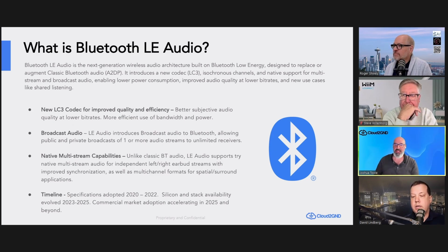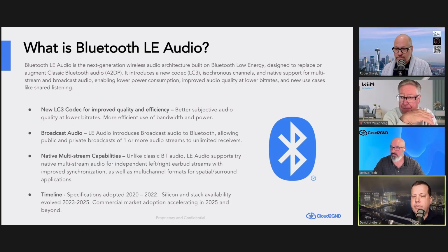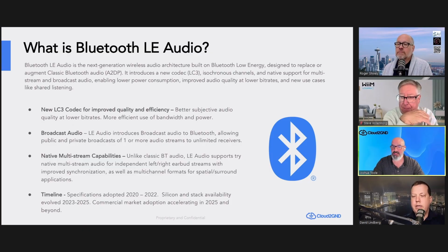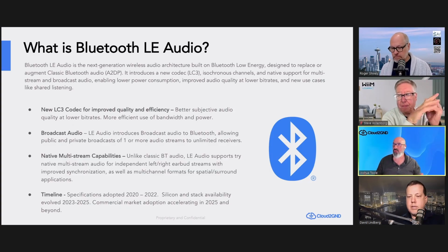So you had Bluetooth LE, which was originally driven for sensors, fitness devices, low power devices, like the initial market. Nordic stuff, all that? Correct. Nordic is one of our partners, and they produce exclusively LE based chips, so they don't support what's called dual mode. Basically, there are two classes of chips in the market. You have LE only chips and you have dual mode chips.